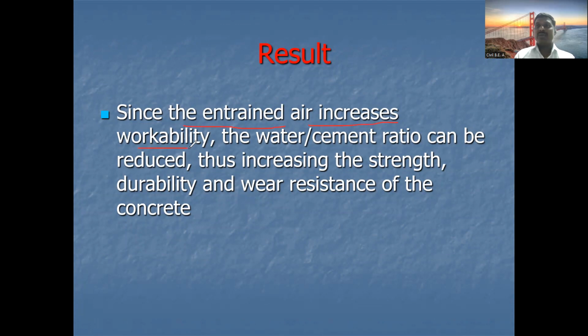Whatever bubbles are formed, those bubbles increase the workability of concrete, and the water cement ratio can be reduced if we use this particular admixture. Due to that, the strength and durability increase, and also the wear resistance of the concrete.